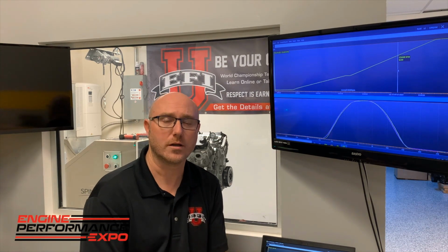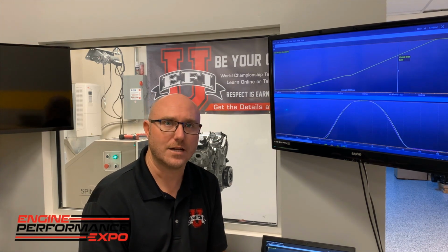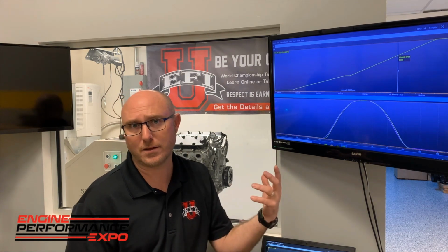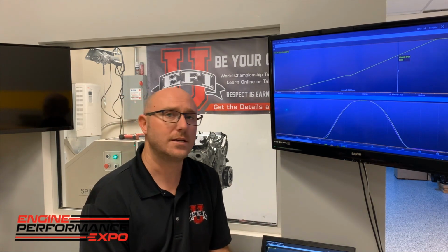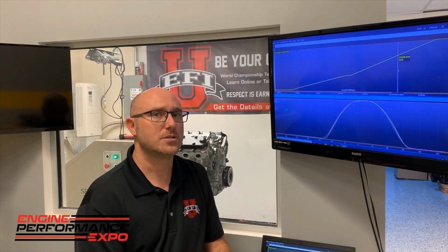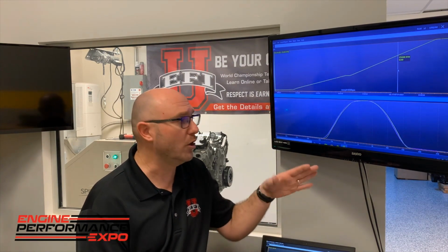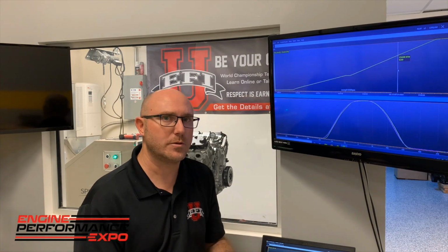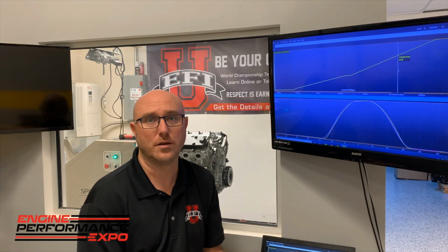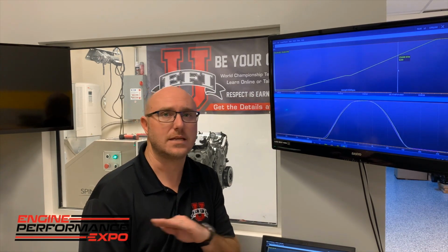And that's when we go to work. We go in there and we check valve lash and we try different valve spring settings. We can shim them up or we can take the shims out and stand them up. We can change the diameter and thickness of the push rods. We can change the lifter configurations. I mean, ultimately we can even change the shape and the profile of the camshaft lobe that's driving all this stuff. But again, it's finding balance between all of those forces and factors that gives us the best approach to making our engine run the way we want. Sometimes what we're looking for is just a stable system.